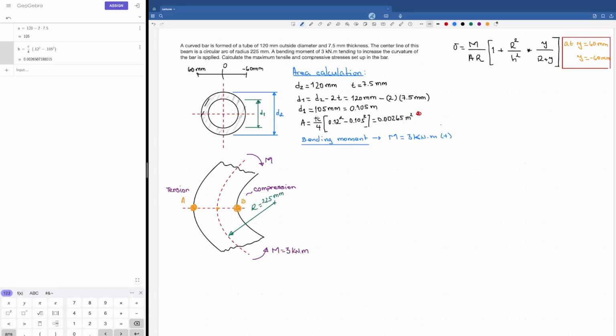Then let's calculate the value for the H2, or cross-section constant. And this cross-section constant is H2. For a round section, the cross-section constant is defined as this value, divided by 16, plus 1 divided by 128 times d to the power 4, divided by the radius of curvature squared, and then plus some other high-order terms.